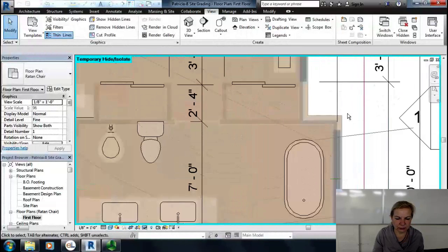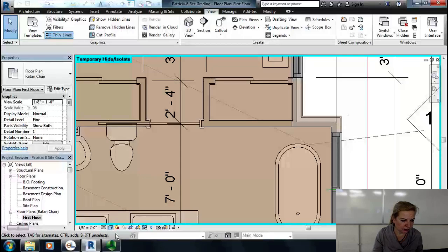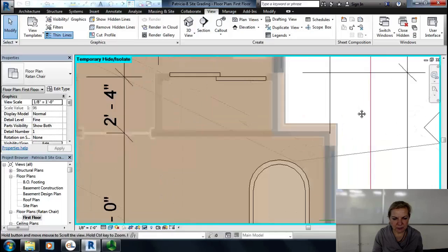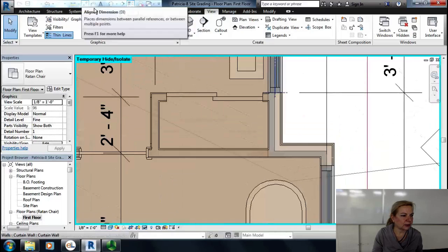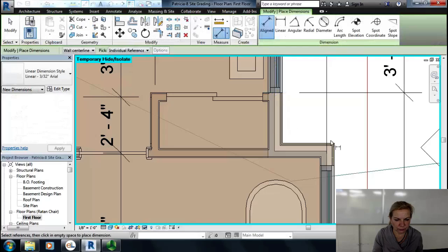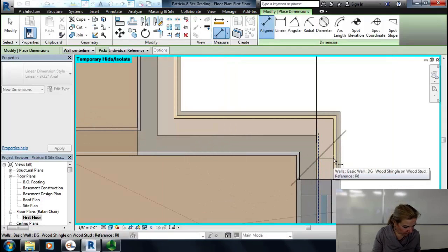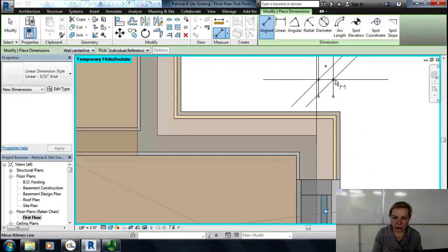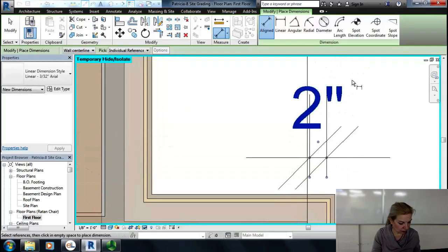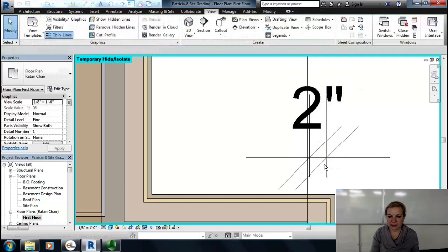Let's go to thin lines so we can see a little bit better, and then to see it even better, go to as fine a view as you can make. And somewhere on your drawing there should be, this is just so you know for future, the offset from center line to, and now you can tab to whatever is important on your project. It could be, in my case, the outside face of my studs. So now I'm tying somewhere, and I could add a note to this dimension, and maybe we should do this.